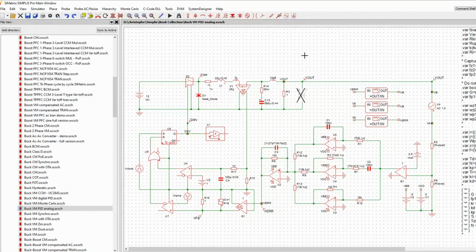Filtered PID means that the classical PID has one pole at the origin and 2 zeros. If you look at the transfer function given by this PID, it's what we call a non-proper transfer function. It means that when s approaches infinity, because of the 2 zeros, you still end up with gain going up with frequency. It will eventually go down because of the frequency limit of the circuit, but it's not easy to meet the gain margin criteria. So what people have come up with is what we call a filtered PID, which is an extra pole added here with the N parameter.